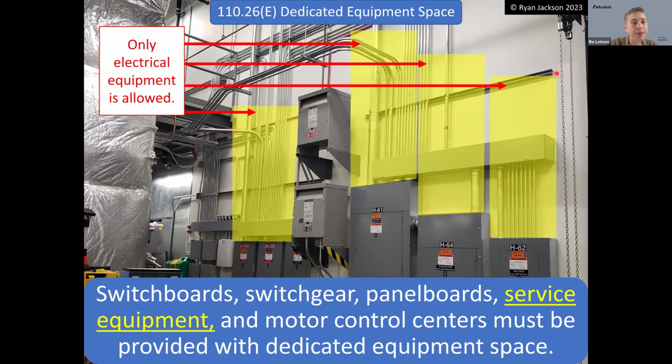All right. Does the wall panel next to the dishwashing equipment need to be ground fault protected? Interesting. I'm guessing we mean the panel board that's on a wall. I think you're talking about that photograph that I had, Brian. I had the stainless steel enclosure. The answer to that is no. We only require ground fault circuit interrupters for the outlet, which is usually the receptacle outlet, but sometimes it could be the hardwired equipment. That's also connected at what we call an outlet. But no, the panel board itself does not require any sort of protection.